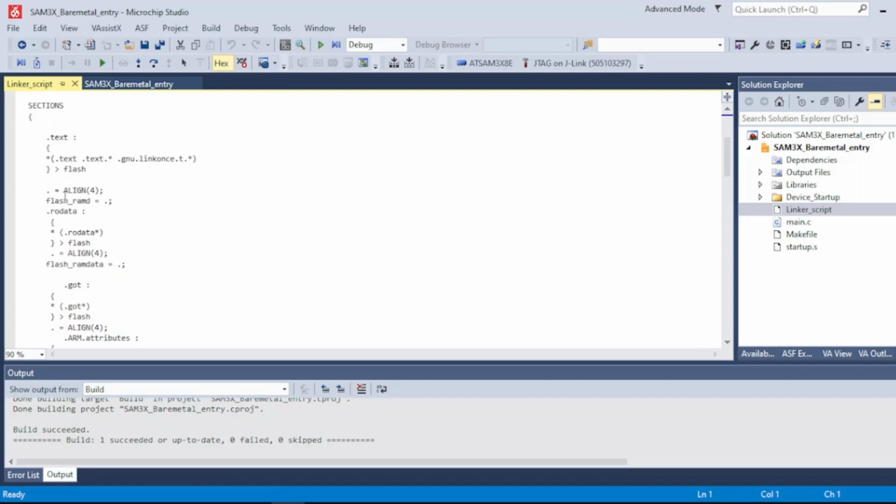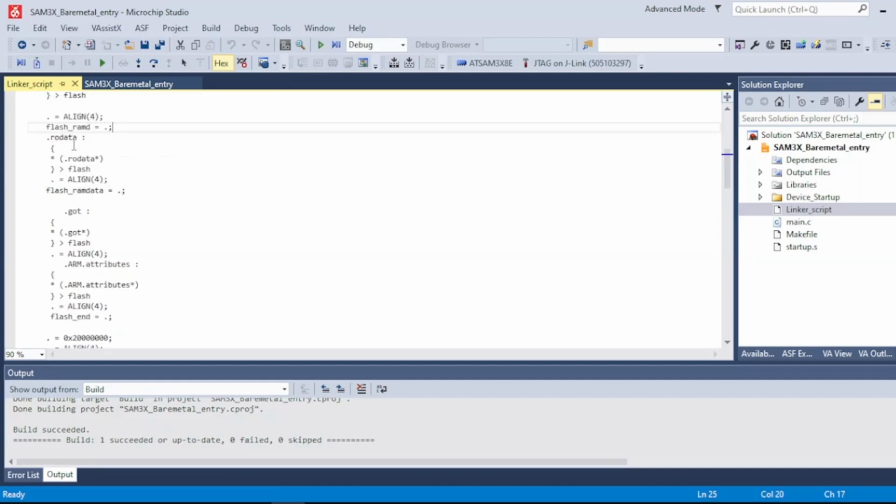As you do so, you have to collect a variable where the text segment is finished, so you can begin placing the data that you have to store next in the RAM. Those are the variable values. After the placing, I use the align again, grab the address where this finished, so I know the size.